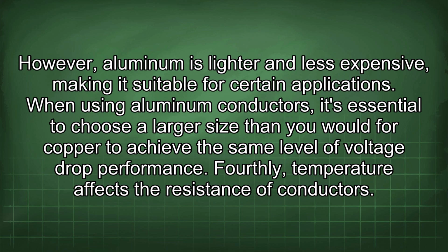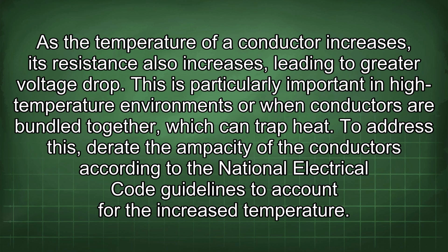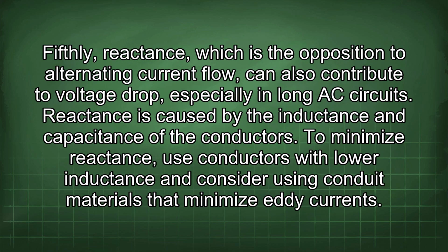Fourthly, temperature affects the resistance of conductors. As the temperature of a conductor increases, its resistance also increases, leading to greater voltage drop. This is particularly important in high-temperature environments or when conductors are bundled together, which can trap heat. To address this, derate the ampacity of the conductors according to the National Electrical Code guidelines to account for the increased temperature.